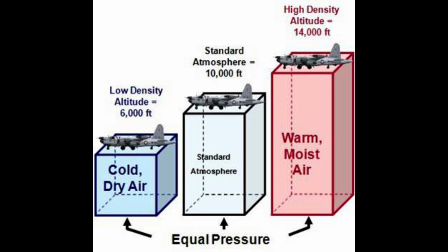Density altitude is used in calculating aircraft performance because under standard atmospheric conditions, air at each level in the atmosphere not only has a specific density, its pressure altitude and density altitude identify the same level. The computation of density altitude involves consideration of pressure, pressure altitude, and temperature. Since aircraft performance data at any level is based upon air density under standard day conditions, such performance data apply to air density levels that may not be identical with altimeter indications.